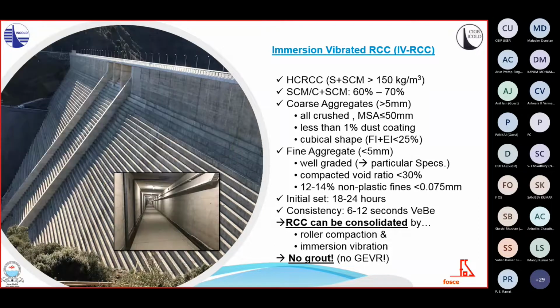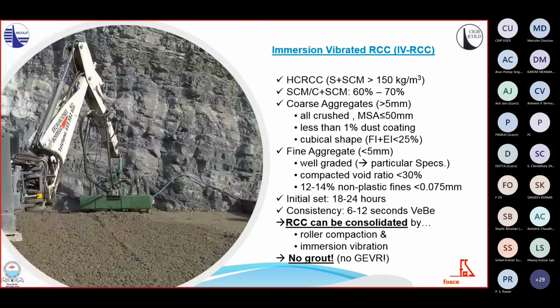And this is Enciso Dam in Spain, a 103 meters high dam that has been recently completed and that is at present at the final stage of impoundment. The dam is showing an excellent performance and no seepage through the concrete. The same mix, the RCC that is roller compacted in the core, is consolidated by immersion vibration at the faces against gallery walls, a detail is shown here, and also against the rock, with excellent performance.